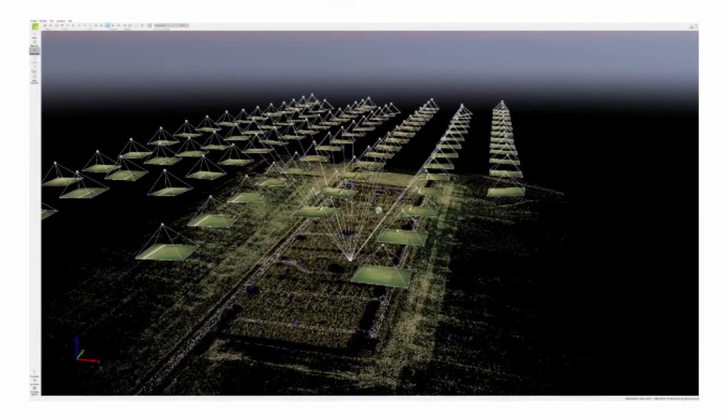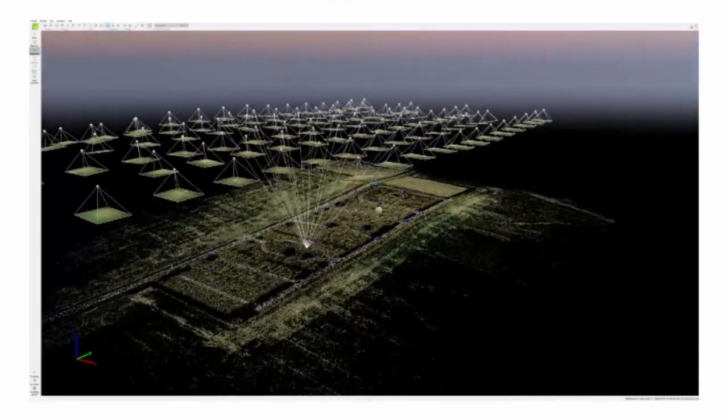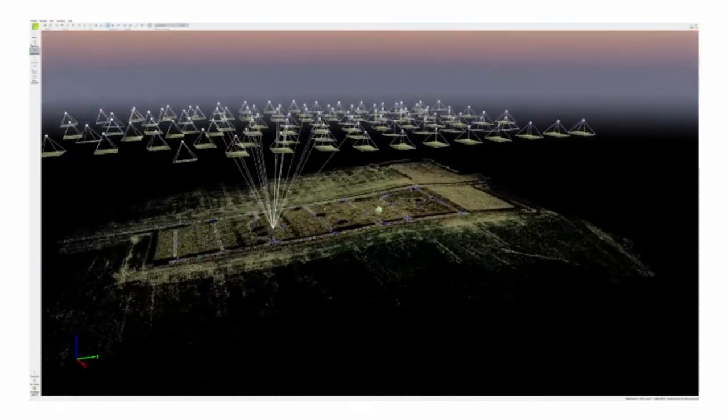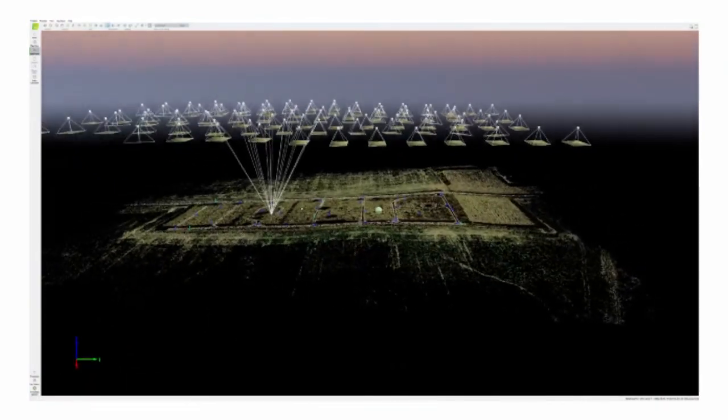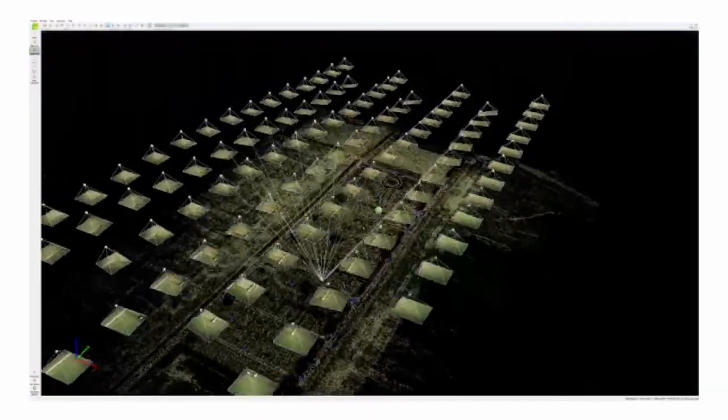Unmanned aircraft also require AT, or aerotriangulation, and significant processing time, often more than collection time. To increase the capacity of unmanned aircraft systems, a few different pieces of technology can help. IMU and GNSS tightly coupled solutions that are post-processed can help reduce the amount of side overlap necessary. Calibrated stable cameras with leaf and mechanical shutters also help increase the stability of models and accuracy. Cleaned DEMs without above-ground features reduce the number of artifacts in UAS imagery as well.